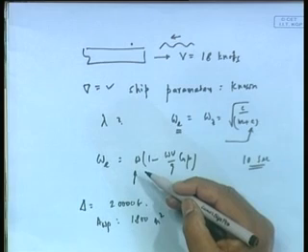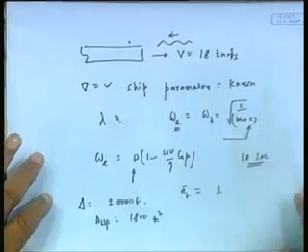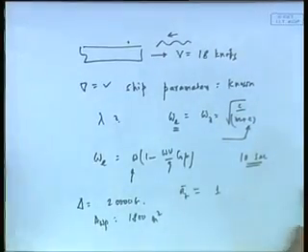I am repeating this because this is a common mistake people make. The other common mistake is in the delta IYY and IYY part in pitch, because people always take IYY for the water plane. If I give a ship's dimensions, they always take IYY to be the moment of inertia for the water plane.